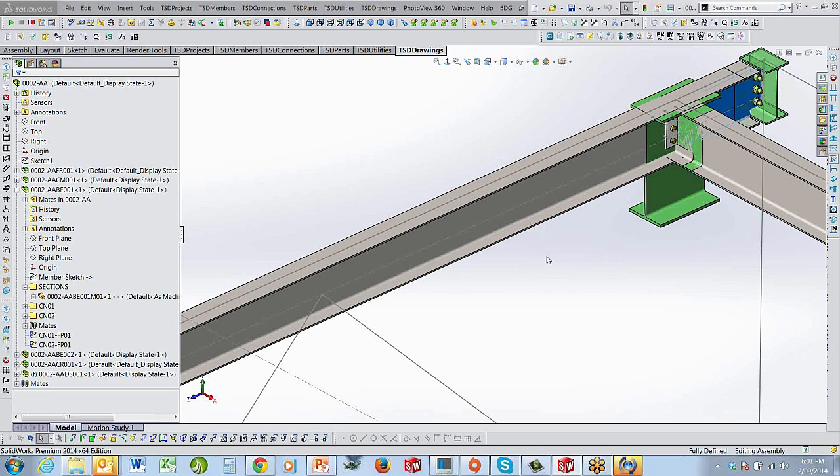We have a 12-digit maximum code. Some CNC machines, which we're working towards for DSTV, only have a certain number of characters that you can use to inscribe onto sections, and that all depends on what machine you're using. So we've got 12 digits as our maximum. We don't want to venture any further than that, and the code that we've got seems to work quite well.